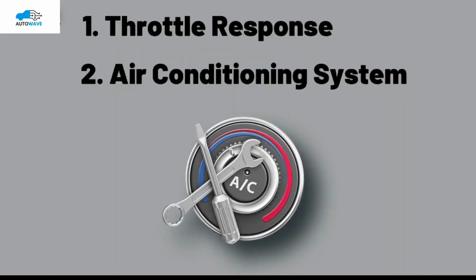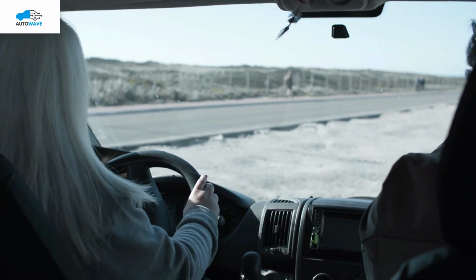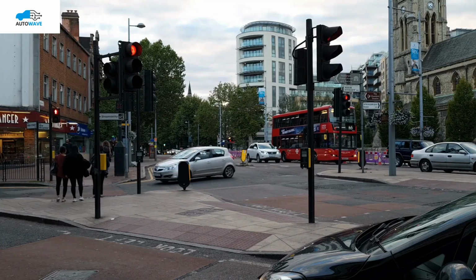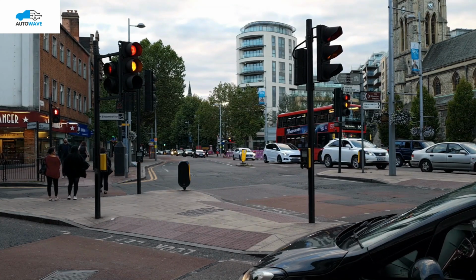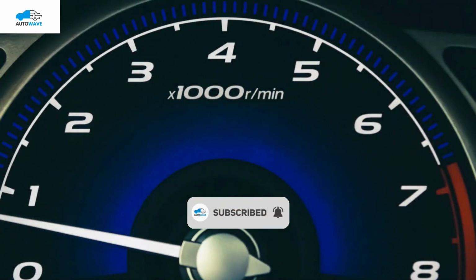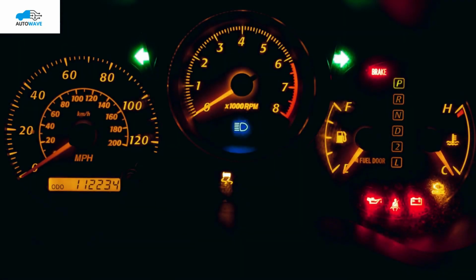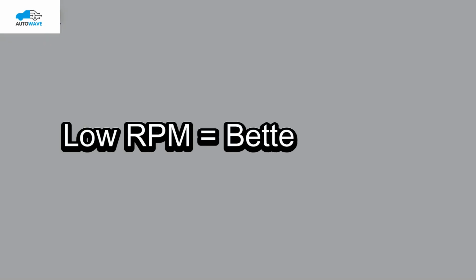Number 2, air conditioning system. Using AC makes driving comfortable, but it also affects fuel average. When pressing the Econ button, the car's AC compressor frequently turns on and off to keep engine load low while still keeping the car fully cool. The advice is to press the Econ button after cooling in hot weather. As you know, turning on the compressor increases engine load, which raises RPM and reduces fuel mileage. However, Econ mode keeps your AC compressor frequently cycling while maintaining your RPM at a possibly low value. As a result, we get better fuel mileage.